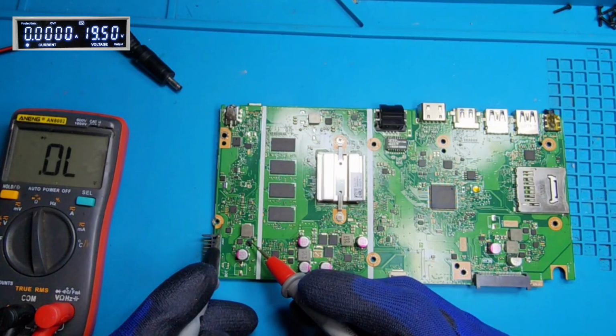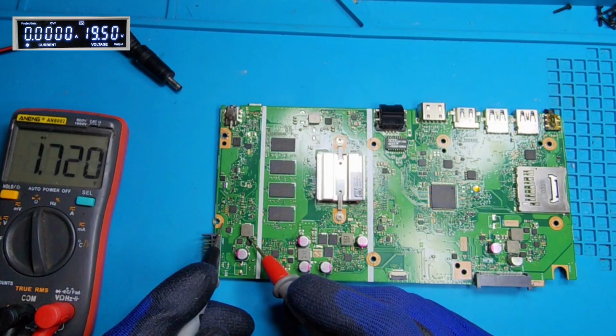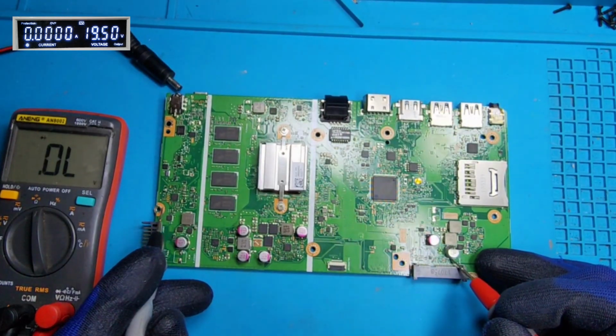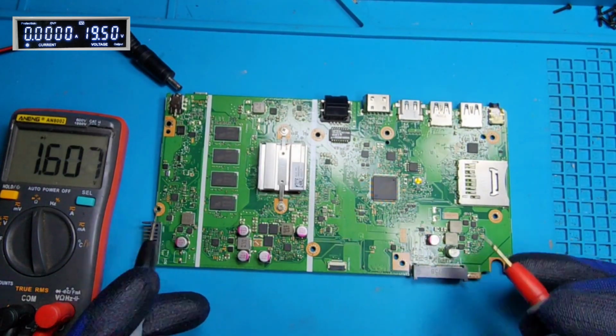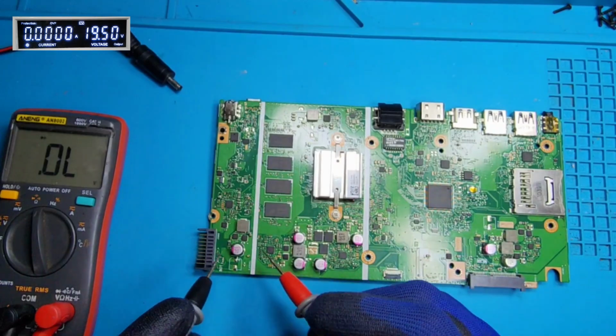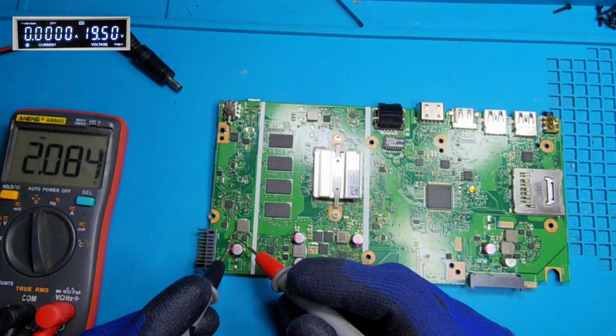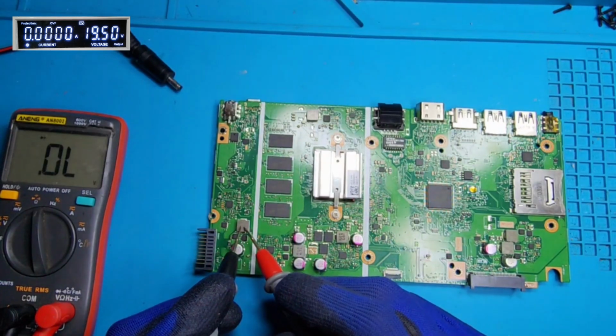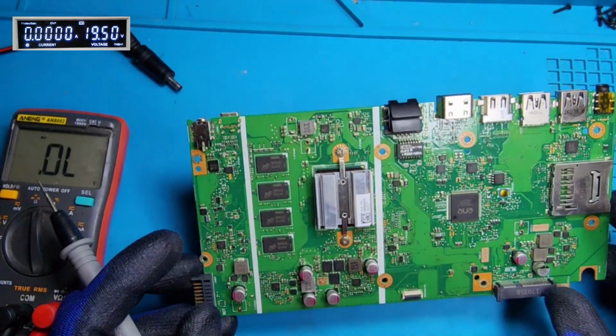That's why it is reading low impedance at this point, equal to the main power rail. If the upper MOSFET got shorted, it acts as a jumper wire from the main power rail to the battery inductor here. So how can we find that?